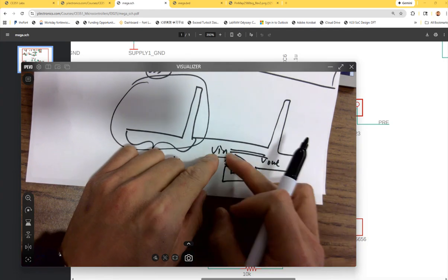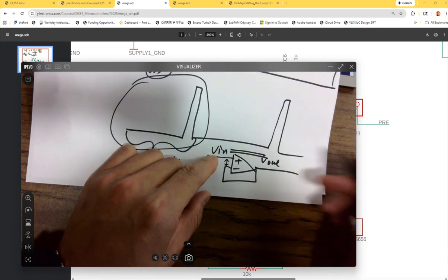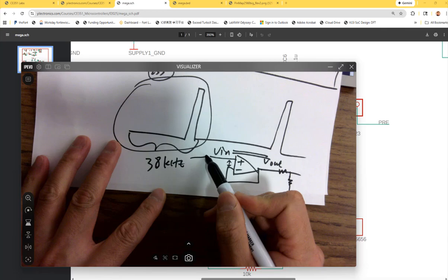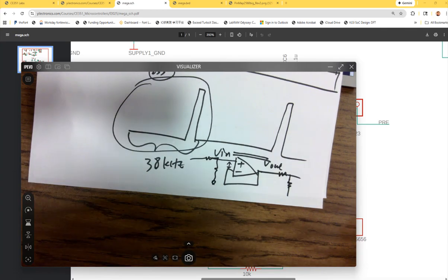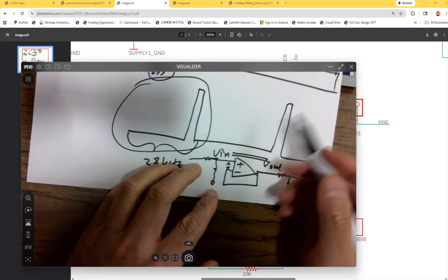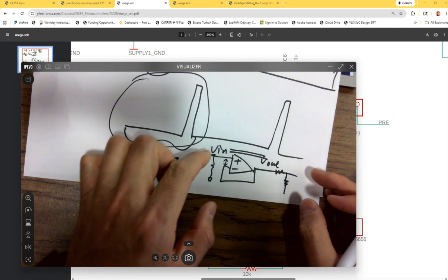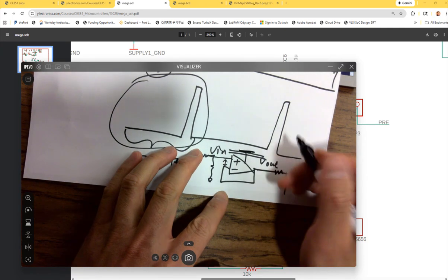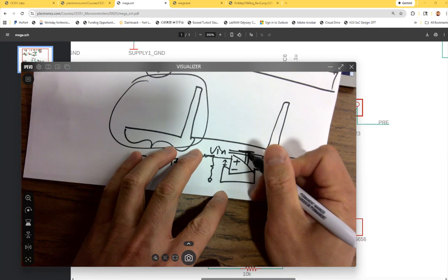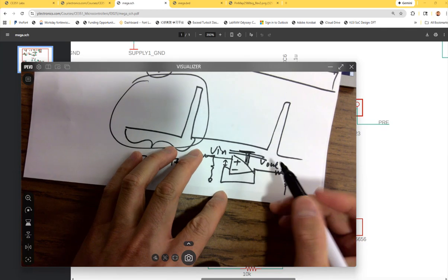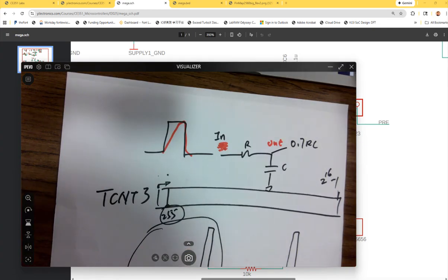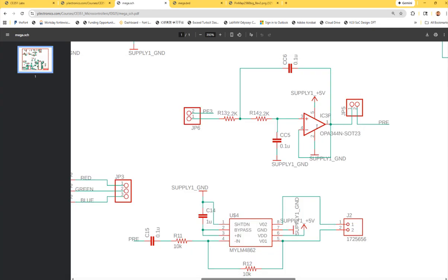So you have a super high impedance in the middle between the input and output. So whenever you are outputting, for example, from a voltage divider, it's not affecting the resistor network at the input. It's totally separated. It's used to separate the input and output, and also used as a buffer, so you can source more power from the VDD and ground. So this circuit on the schematic is a voltage follower.